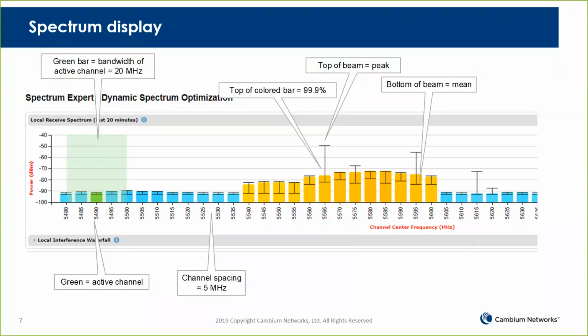Generally speaking, if that channel stays like that, it might be a good one to avoid, because those peaks are very hard to mitigate against, and they're unexpected, and that's a bad choice of channel. And then we should point out there is a color code. The blue ones show interference level below a threshold. I think the threshold here was set at -85.